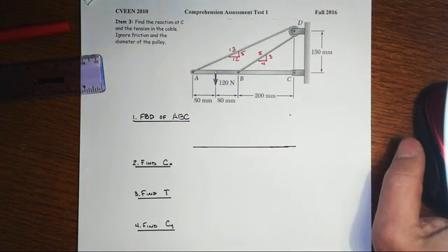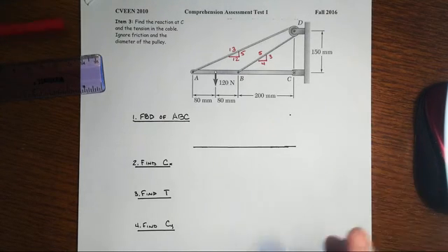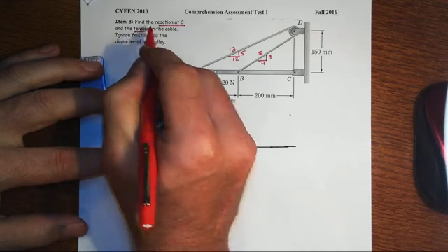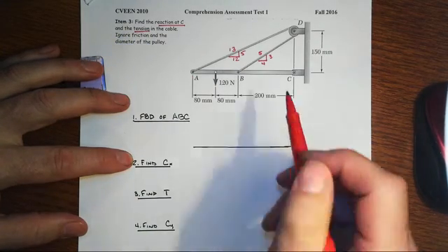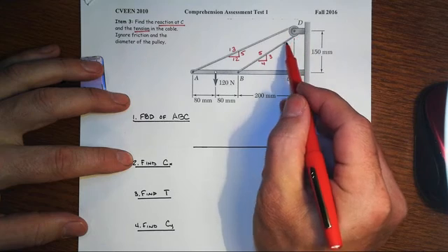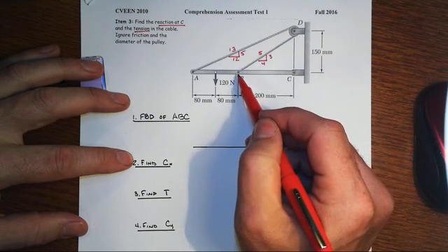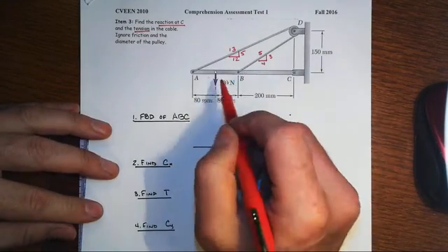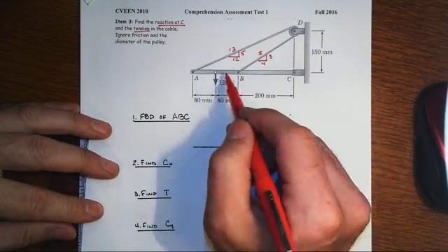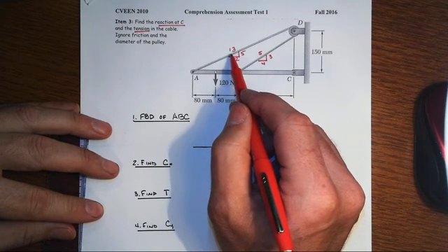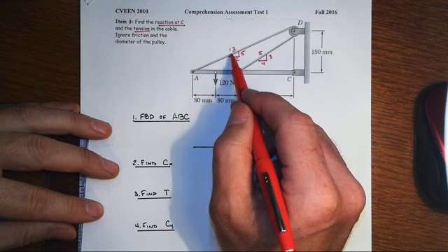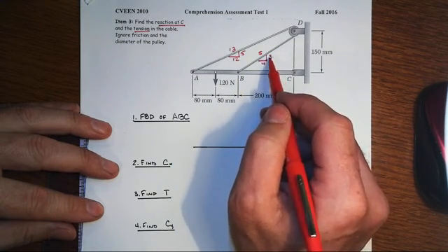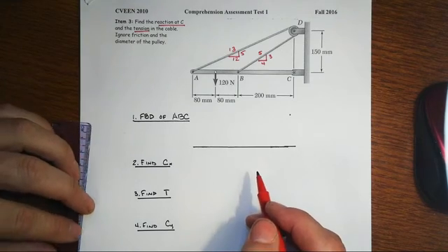In the third item on the first exam, you're asked to find the reaction at C and the tension in the cable, noting that there is only one cable, which wraps around at D and is attached to the beam at points A and B. I have also already taken a look at the right triangles that represent the angle of inclination of the cable segments. On the top, it turns out to be a 5, 12, 13 triangle, and at the lower level, that's a 3, 4, 5 right triangle.